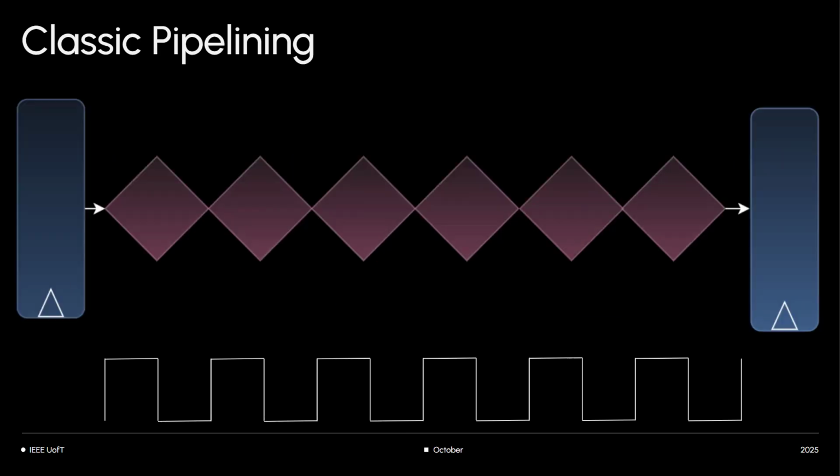A simple analogy would be, if you guys are making cake at home, right? And let's say it involves 10 steps, and it's just a single person doing the whole 10 steps together. If each step was a clock cycle, it's going to take 10 clock cycles for a single person to get done. But how about this? You have 10 people, each one works on one step. They do it, and then they just move it to the front of them. That way, once your pipeline fills in, once everyone has some tasks to do, you're going to be shipping out one cake every clock cycle.